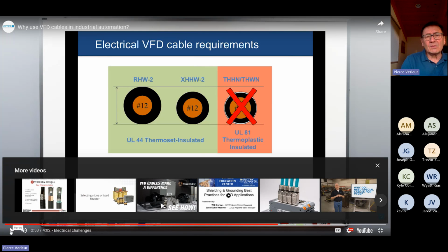That's one of the differences, by the way, as a little side note, between the quality people that make drives, the Yaskawas, the Siemens, the ABBs, Danfosses of the world, and the drives coming in from a manufacturer that you may not recognize that is not compliant to the NEMA MG1 Part 30 and 31 specifications, and therefore is using a one-size-down transistor, but switching it on very fast.